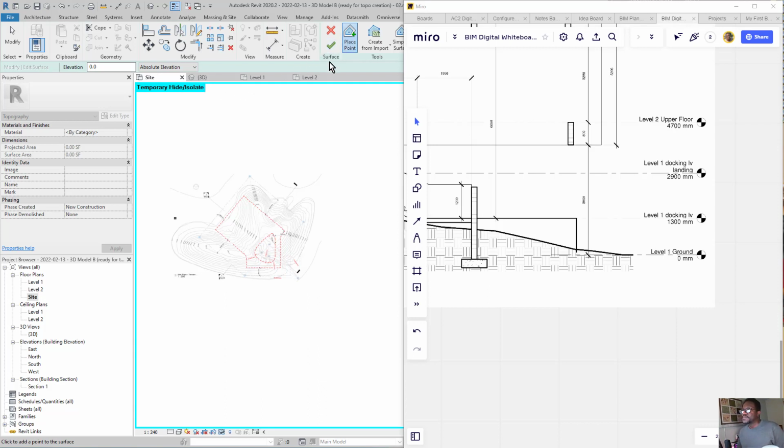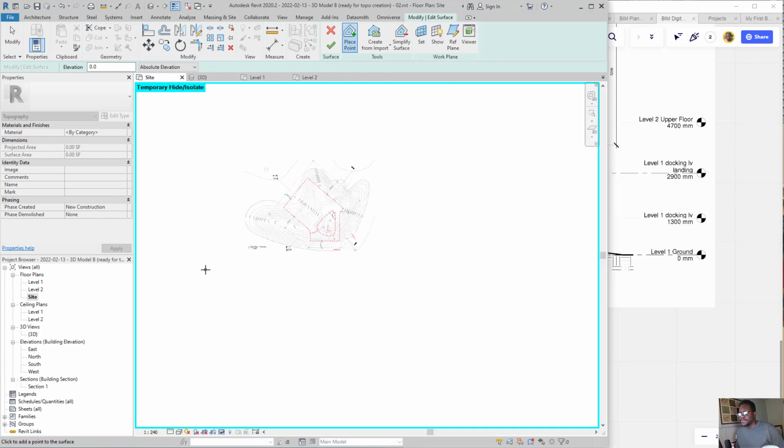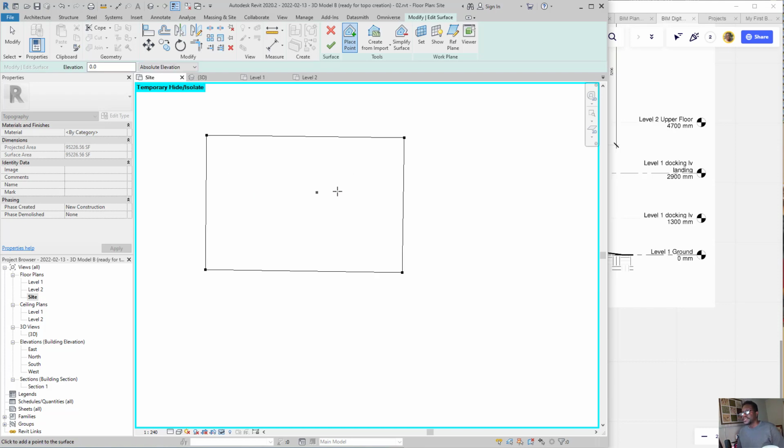So for example, I'm going to go to create point, make sure that is selected, make sure that it is on level 0, and then I am going to create these points on the outside of my drawing, about right there. Once I have that created, I'm basically just defining where the edges of my contours will be. Now I can always go in and edit this later, but you want to do this so that it encompasses pretty much your entire scene, your 3D scene.